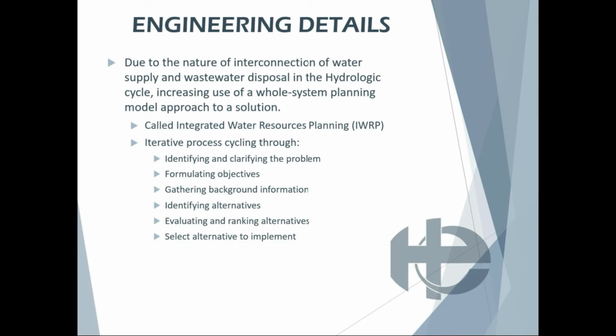What information do you have available in terms of potential sites that can reuse this water? What alternatives do you have for treatment? You rank the alternatives, you try and select an alternative to implement, and you investigate some of the economic aspects. Maybe it turns out that your first choice isn't going to be economically viable, so you go back up and start the process all over again with a different treatment alternative.